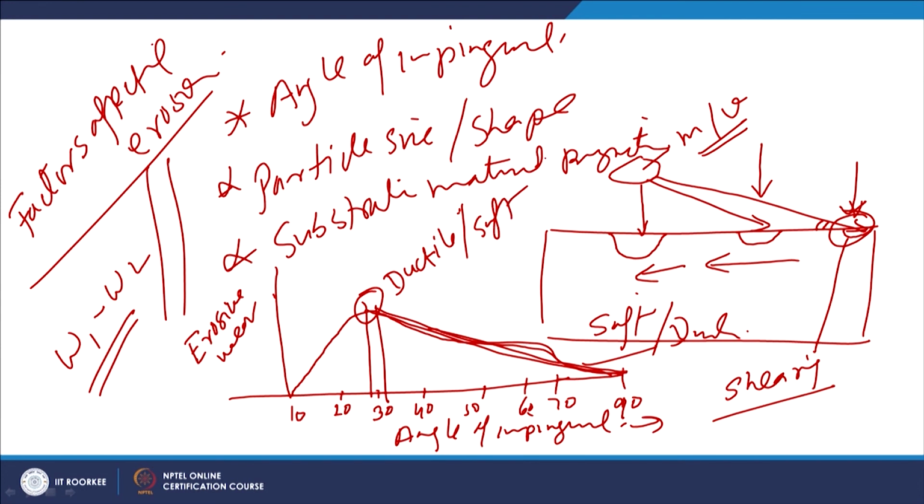So, this is one thing. To deal with this difficulty, for those metal systems which will be experiencing erosion due to impingement of erosive particles at low angle, it is good to increase their hardness so that the erosive wear resistance can be enhanced, but this hardness also has to be increased only up to a limit, otherwise it will backfire and start increasing the erosion.